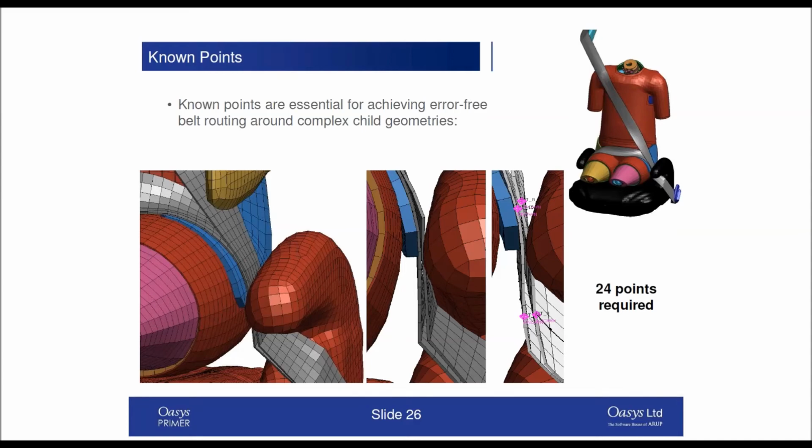I required the preset for the child, so the radial vectors settings, the offset settings, and then also for this particular example, I needed to switch to the mixed mode of path. So rather than use the spline, the curved version, I had a mixed version. So it wasn't purely linear. I did keep some curvature, which I needed over the chest, but I found that having the mixed mode worked well to try and navigate this very thin path between the occupant and the booster seat there.